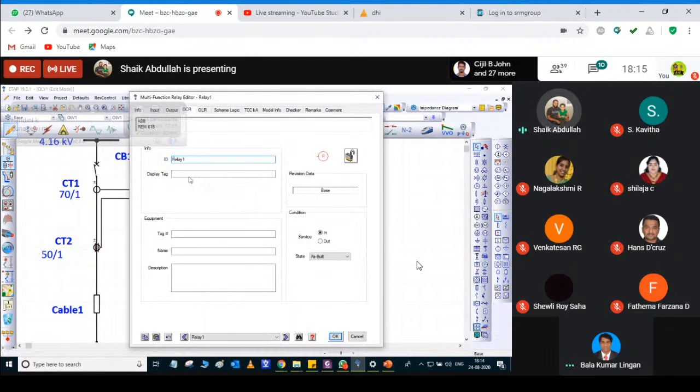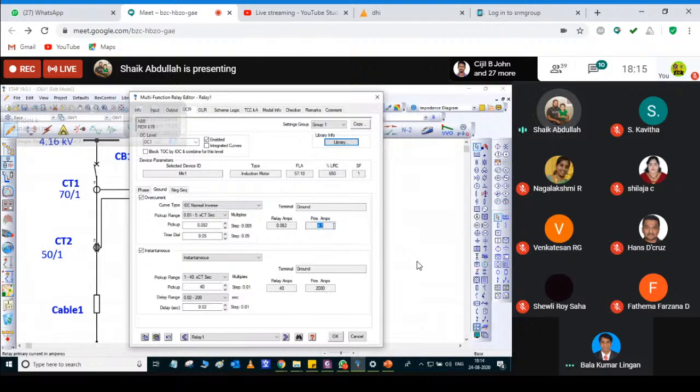And what about the relay? Now we'll go to the ground setting, so you will get the amps right now because you already gave the value. Before, it read as 0, but now the current is very low, 4 amps. This 4 amp current is going to be sensed by your high sensitive ground fault protection, whereas in your phase the current is 62 amps, and in ground the current is very minimum, 4 amps. So this is nothing but high sensitivity achieved by using CBCT. That is the important one.